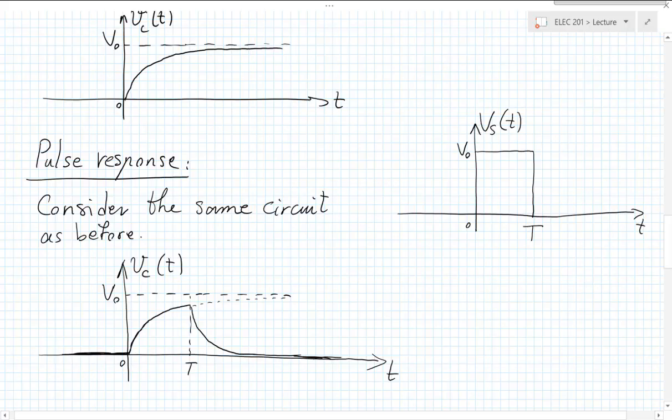The capacitor voltage. So there is a question here as to whether the voltage of the capacitor has to persist for a small amount of time at time t. How small would that amount of time be? 0 in duration is the correct answer. In other words, the capacitor has no problem changing the trend in its voltage instantaneously. It doesn't like to change the value itself abruptly. And I hope my drawing here doesn't make it look like it's changing abruptly. It's really just that point.